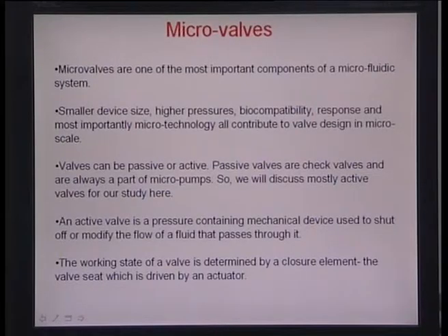So what all is important for valve designing? You have to consider the size of the device. These MEMS devices are very small. You have to consider pressures which are very high. That is why most of the pressure sources sometimes are off chip. Okay, the mechanisms of valving involves energy sources or pressure sources which are not on the same chip. We should be aware of biocompatibility issues if we are designing valve materials or choosing valve materials. The valve should have a proper response to the flow processes, and most importantly microtechnology should be used for fabricating such microvalves, particularly for using or gating the flows in micro scale.